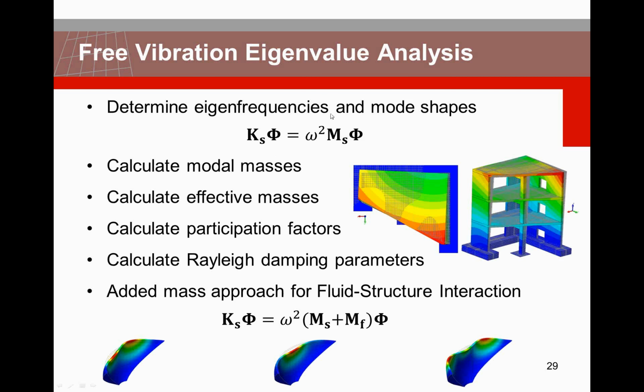From these eigenmodes and eigenvalues, which will be found from this analysis and can be found in the DIANA output file and in your output results, we also calculate some typical mode and model related numbers such as the modal mass and the effective mass, which is the amount of mass that is moving per mode, also as a percentage of the total mass.